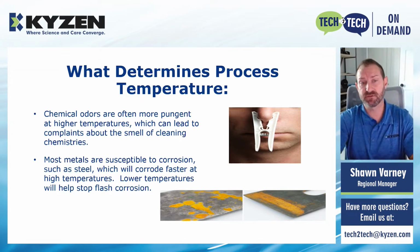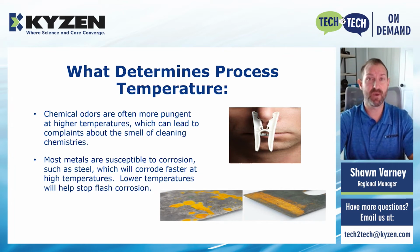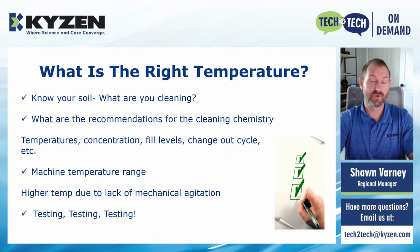Most metals are susceptible to corrosion, such as steel, which will corrode faster at higher temperatures. Lower temperatures will help stop that flash corrosion. This is where you might introduce a CP or RP product, a corrosion prevention or rust prevention product, into the chemistry to fix that issue. So what's the right temperature?